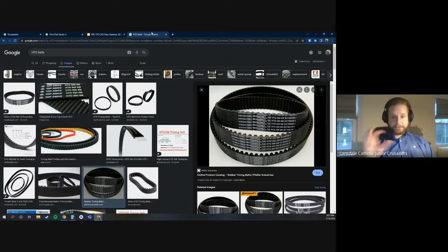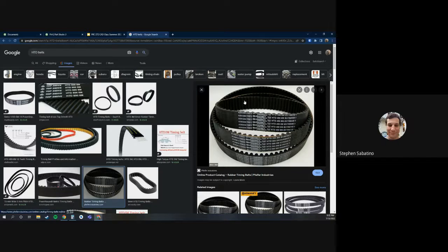A belt can also have a smaller minimum size sprocket, so it can take up less space and have a larger reduction in a smaller gap. With a sprocket, you can only really get a 4-tooth sprocket, I think, as the minimum. And a 4-tooth sprocket is the same outside diameter as a 10-tooth belt pulley. Does that help answer your question? Yeah, I think so. Perfect.